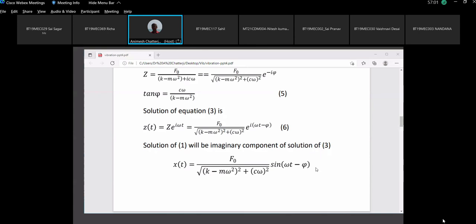So this sentence, that vibration will never die, means that if the vibration never dies out, there is a possibility it will lead to fatigue failure. The possibility is definite if the stress is above the endurance limit for steel. If the stress is below the endurance limit of steel, fatigue failure will never occur. But if it is aluminium, definitely the failure will take place. So that is how this sentence is important. But in today's discussion, I am expecting more important sentences.